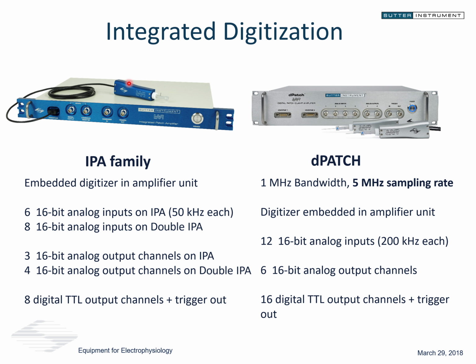In fact, for the patch amplifier, the preamplifier section, the analog section that's mounted to the head stage, is a separate box, a separate entity, and in that entity it has the calibration constants and its own independent A to D and D to A converter for that particular head stage. So those can be easily swapped around. If something is damaged there, there's no need for calibration because everything is stored in an internal EEPROM. So those can be easily changed, swapped out.